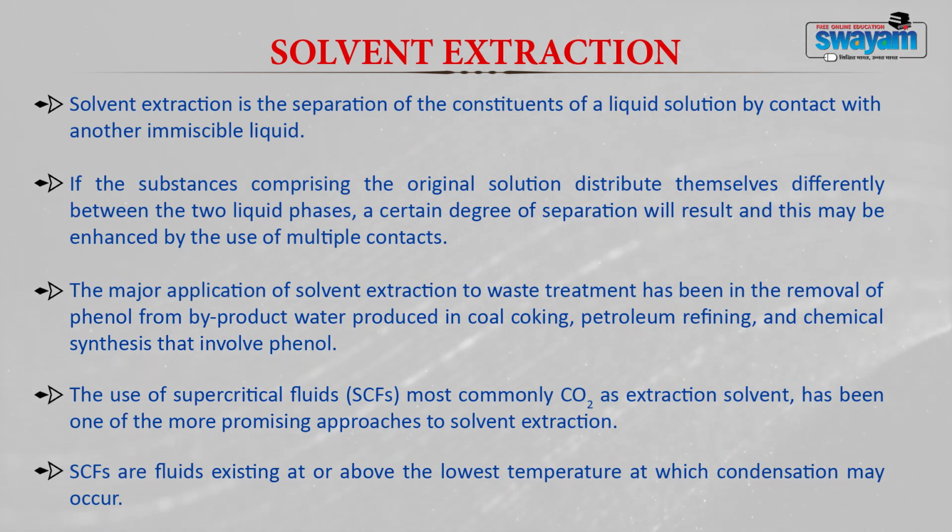extraction process. Now, distillation. Distillation is again an expensive and energy intensive process and can probably be justified only when you want to recover certain valuable products like solvent recovery. This technique has only limited application in the treatment of dilute aqueous hazardous waste.